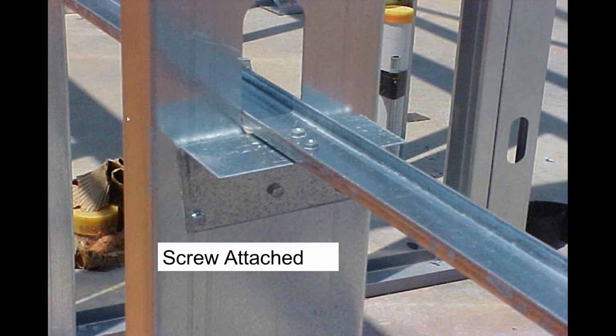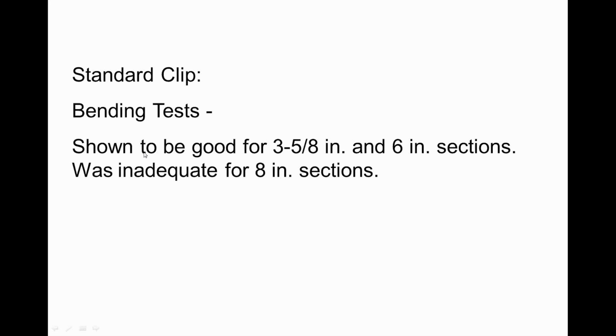Does it work? Based upon some testing I was involved with several years ago for bending, which we felt was more critical than axial load, we found that for a 3 5/8" section and a 6" section, that assembly worked very well. The 8" section, it did not. So we need to think about our bracing as we look at bracing through the punch-out for an 8" deep section, and watch the length of that standard angle especially.